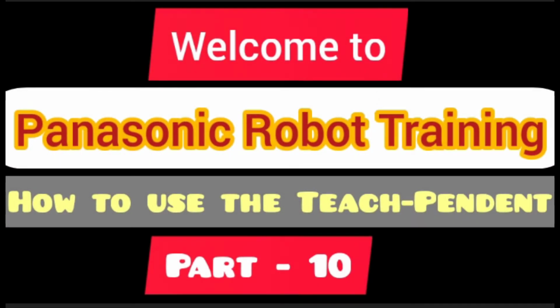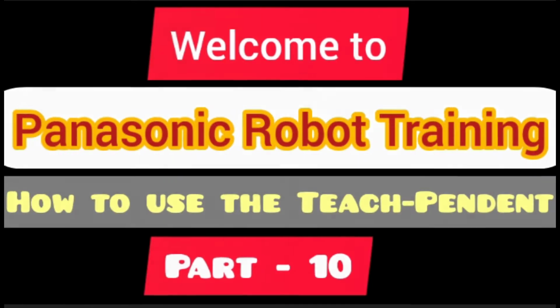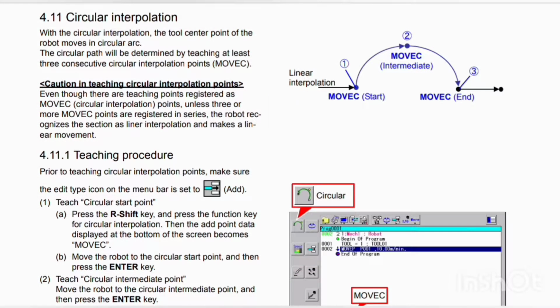Here we discuss part 10. Today we discuss circular interpolation. With circular interpolation, the tool center point of the robot moves in a circular arc. The circular path is determined by teaching at least 3 consecutive circular interpolation points.